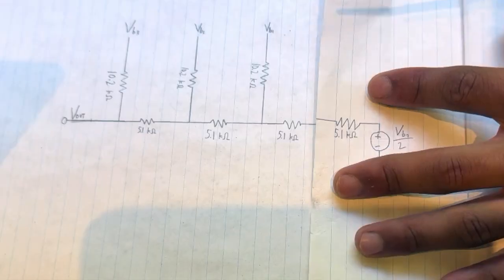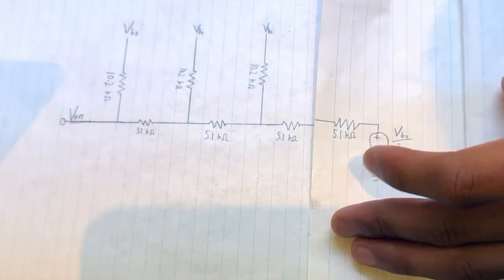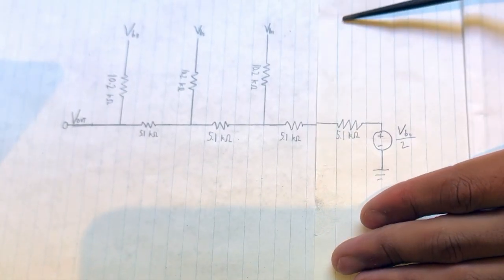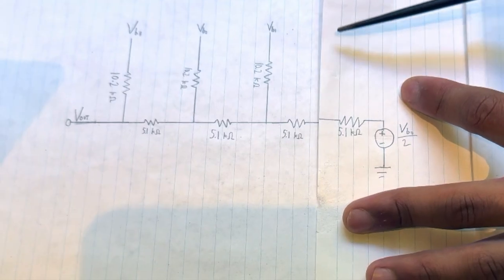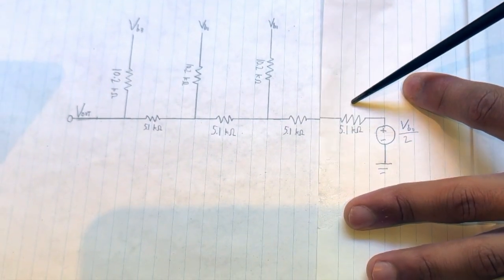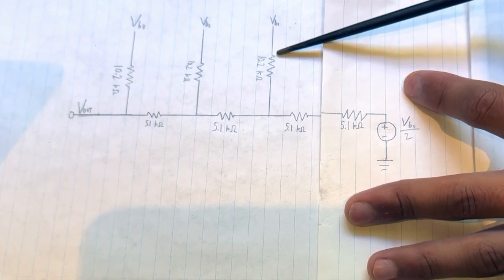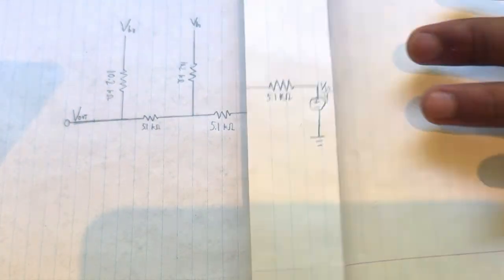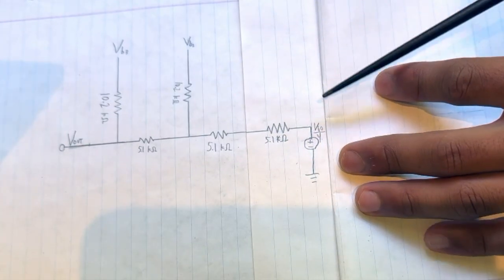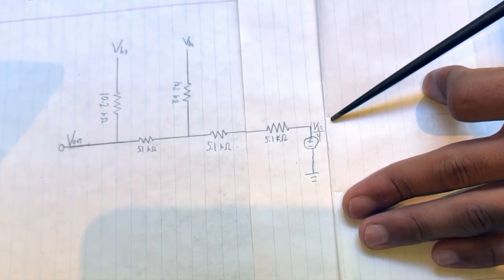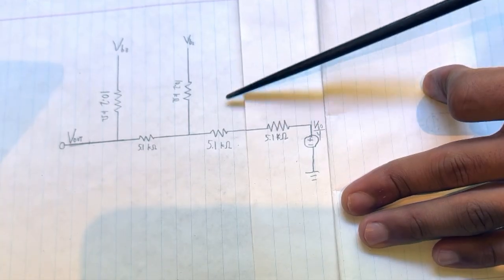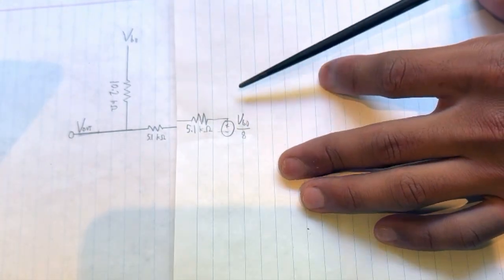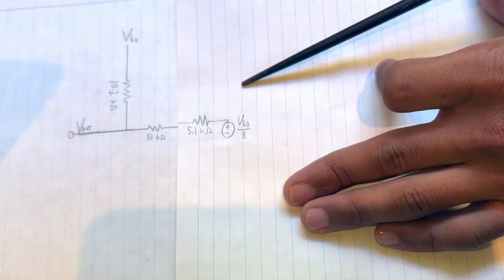This can be replaced with one resistor, and this is from Thevenin. We know that, and B0 divided by 2. Now we have a similar looking circuit with one 10.2K, because these add, and then in parallel with another 10.2K. So we know here the voltage contribution will be half that again. We have that replaced with this, and now it's a quarter of bit 0. Now again we have the same thing, 10.2K and 10.2K. Here we would see an eighth of bit 0's contribution.